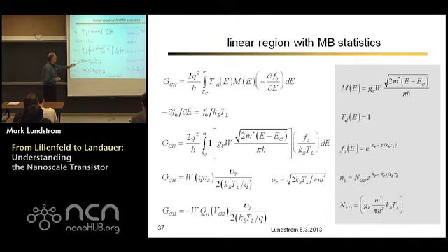Q times the carrier density per square centimeter is just the inversion level charge. The amount of charge we have depends on the gate voltage. So now it's starting to look a little more like a MOSFET. And this collection of constants here turns out to be just the average thermal velocity of electrons randomly moving around inside a semiconductor. V sub t is the thermal velocity.